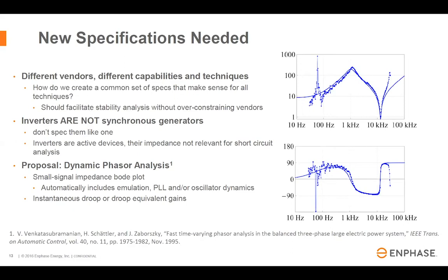Because a Bode plot in an inverter data sheet would allow for a variety of different controllers, characterizing the dynamics of that controller in a standard way despite what controller you're using. So if you have virtual impedance simulation, if you have a PLL that introduces some impedances at different frequencies, a Bode plot would include all those dynamics, right?